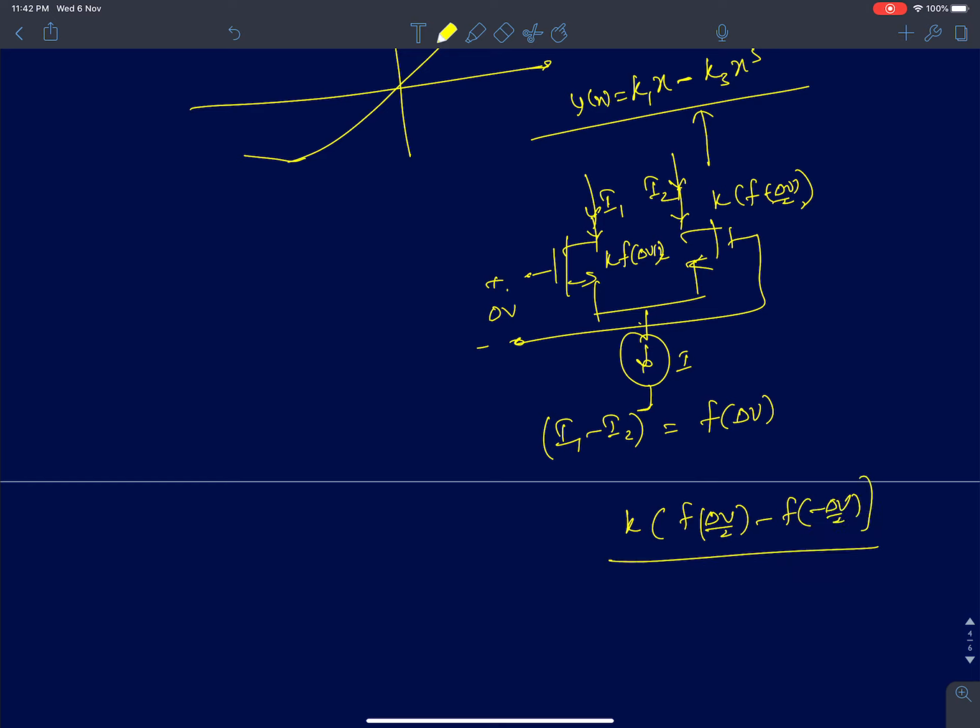If you look at this, the function is an odd function, which means it will only have odd harmonics of the input frequency. And usually the harmonic strength keeps reducing as you look at higher and higher harmonics, which means the strength at f1 will be much greater than at 3f1, and 3f1 will be greater than 5f1 and so on.